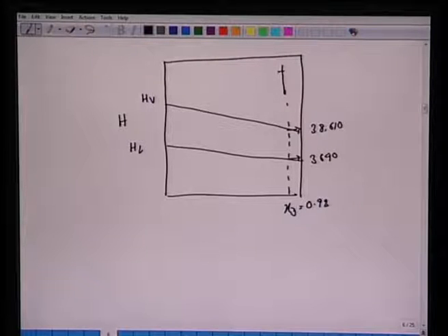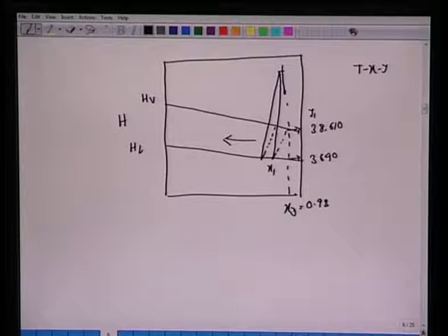Now, had we known this, then of course for the first point, this is Y1, we could have drawn the tie line from the TXY diagram. So given Y1, we could have got X1, we would have connected this with this delta D, then got another point here, and got another equilibrium tie line. And then we would have proceeded like this: stage 1, stage 2, the first operating line, the second operating line, etc. Now how do we get R min? We also said in our previous lecture that to get R min, one has to monitor the locus of this R min as it goes up or down by changing this reflux ratio, which is L0 by D.